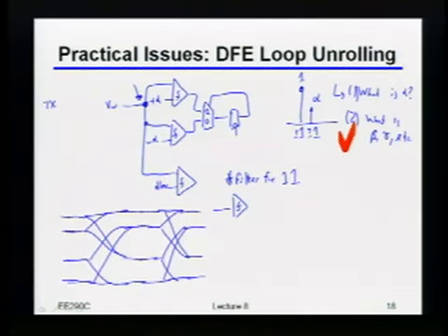So for number 2, you just filter the data to find any one of these 4 levels, and then you can close all of the same LMS loops we talked about before to adapt all of the rest of the equalizer coefficients. Okay? So that indeed works. Now, how do you answer number 1? How do you find alpha? And by the way, this exact question is why I'm not the biggest fan of loop unrolled DFEs, but we'll come back to that later.